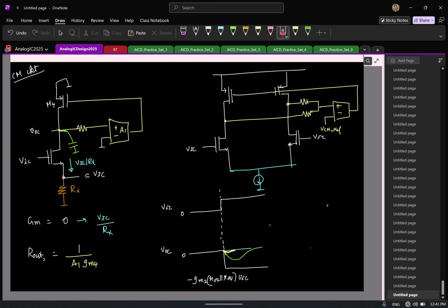So if you have a common mode rejection in your circuit to begin with, in the form of a tail current source, that first of all reduces the short circuit GM for common mode signals. So the common mode current getting pushed into the output is going to be really small. So even if there is a delay in the common mode feedback loop, your output common mode will not change a lot. That is why in practice we prefer doing this, because this gives a first level of security. Now the CMFB provides a second level of security against common mode jumps.